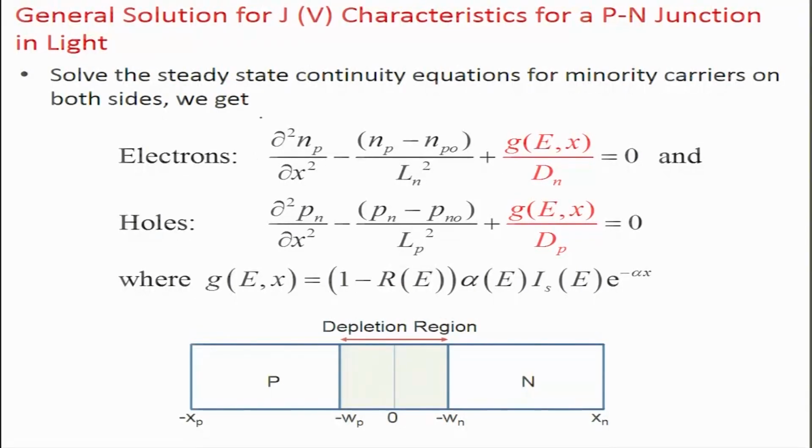Remember we used to have D on this side, which we have brought here, because this equation is basically del of J. In this case we are taking Jn diffusion minus R, which is delta n divided by tau n, and now we have taken the generation term, small g. This is the continuity equation.